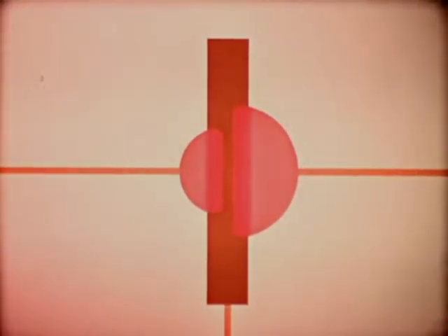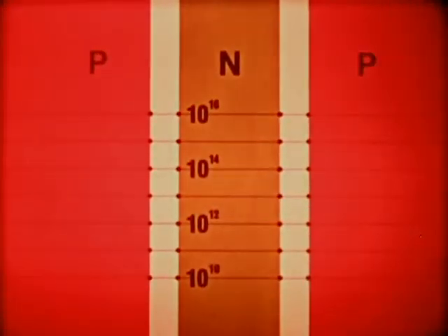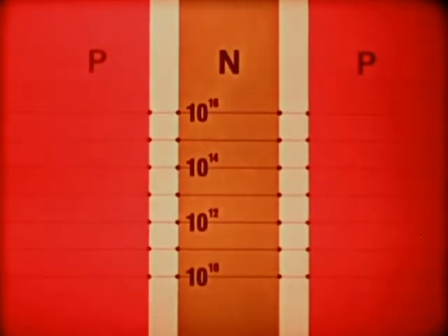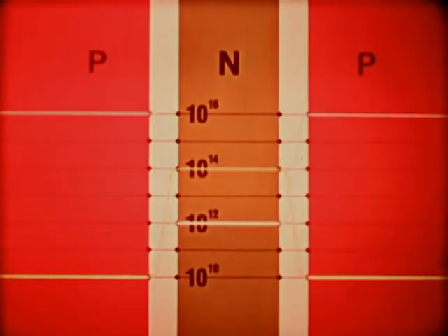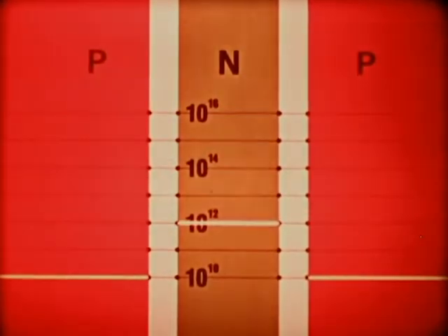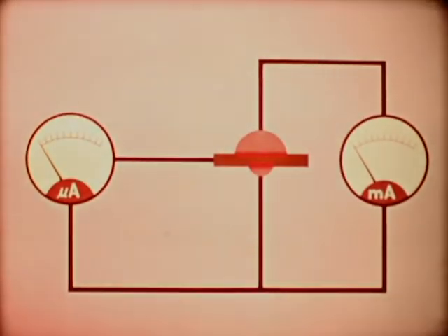In a PNP transistor with no external voltage applied, the concentration graphs of majority and minority carriers in the neutral parts of the P and N regions are horizontal. No current flows in the external circuit.